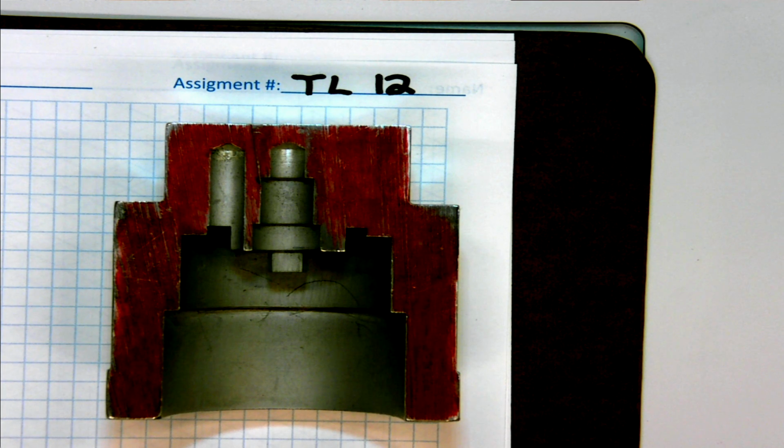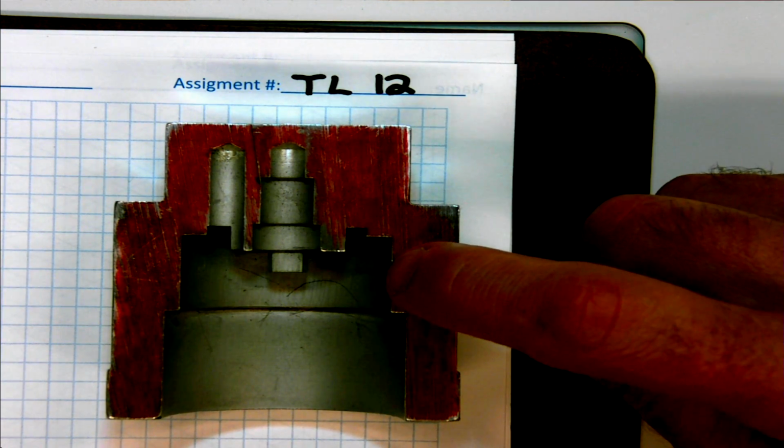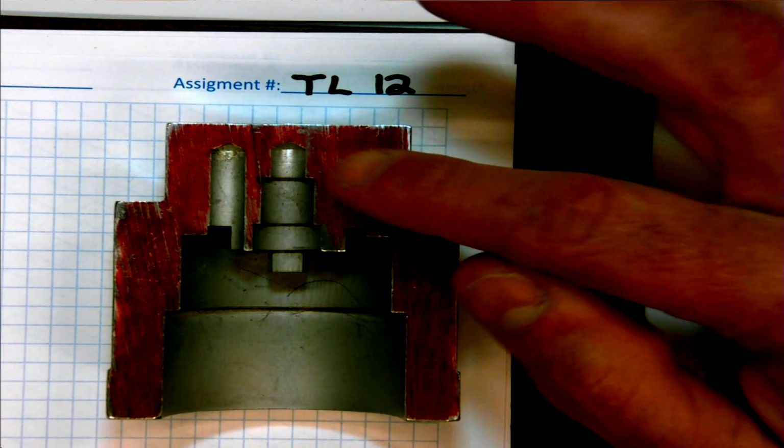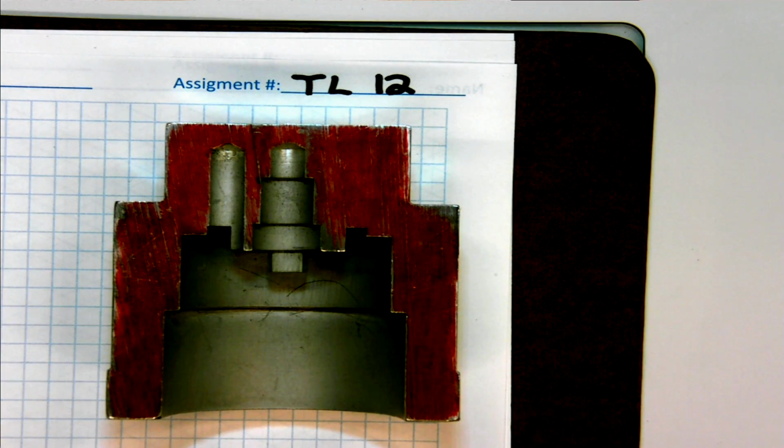Now in the CAD world, a lot of times now, you take a cutting plane and basically cut it through an object to do measurements. Let's say to measure from this edge here to this edge here, to take this cross section here and make a copy of that cross section and put it into a Sketcher-based operation and create features from it. There's multiple ways you can use these section views.